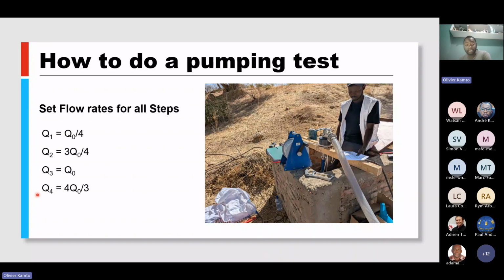The total duration of the variable rate pumping is such that during this step, if the pump runs 1 hour, 1 hour 30 minutes, then the drawdown should stay at the level of the pump limit, so that we avoid a dry run scenario.